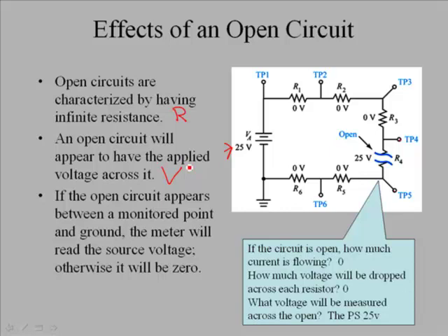And people wonder, well, why is that? Well, consider the fact that when this circuit is operating correctly, we have current flowing through this circuit. We have that loop, which is a requirement for all circuits. Now, when this component opens, we no longer have that loop. So now there is no current flowing through these components, and you might notice the little 0 here on all these components indicating 0 volts.